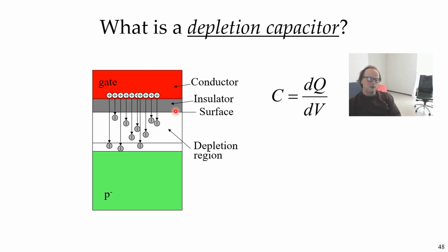So let's see what happens if you now put some charge on, like I just did. You need more charge, but you can't get it from these fixed ions because you used up all of them, all they're terminated to. So when you add more charge, it's going to appear further away, right? That's why it's a depletion capacitor, as I talked about last time. As you increase the voltage on this depletion capacitor, the incremental capacitance actually gets smaller.